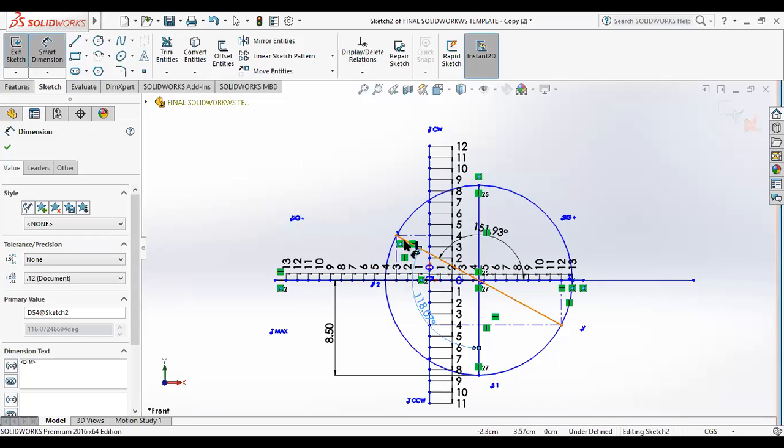In my Mohr circle, it is 120 degrees. When I am representing it as a sketch in x and y coordinates, not in the Mohr circle, I divide by 2. When I am converting into the Mohr circle, I have to take twice the angle. Since theta is given as 60 degrees, from the x point it is clockwise 60 degrees.